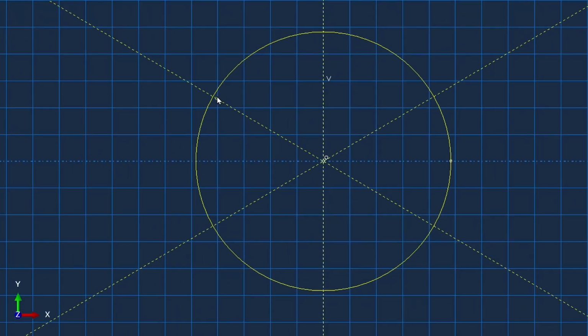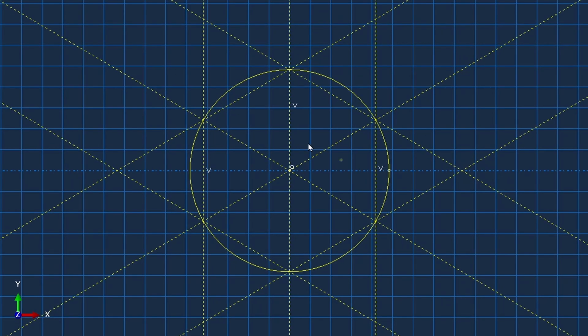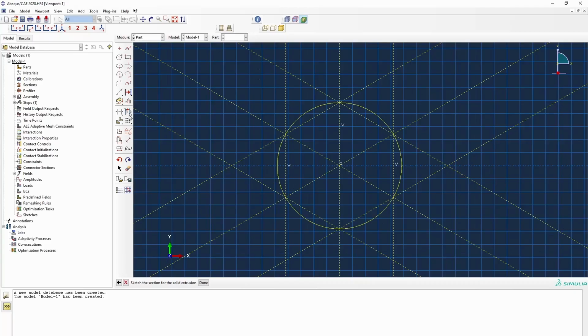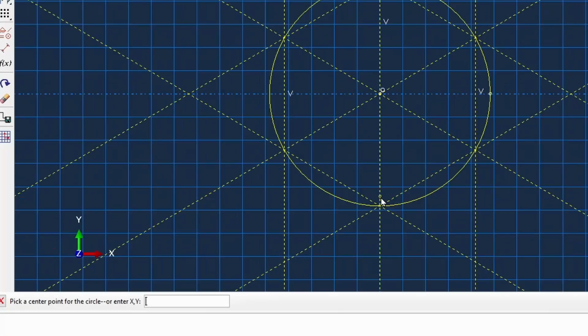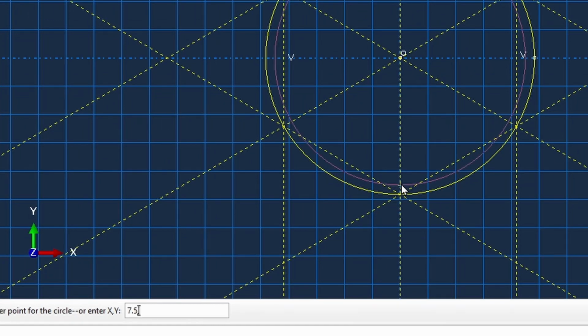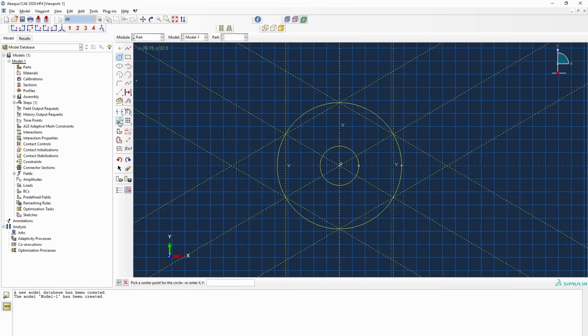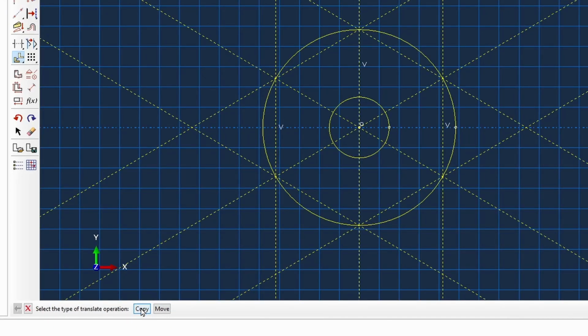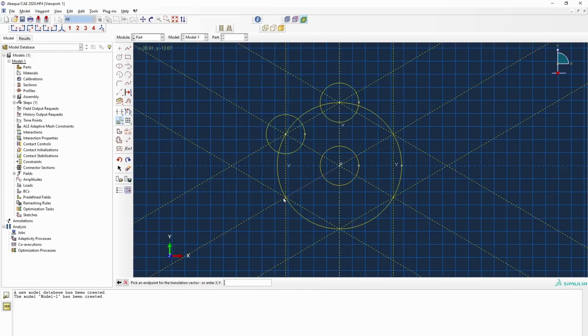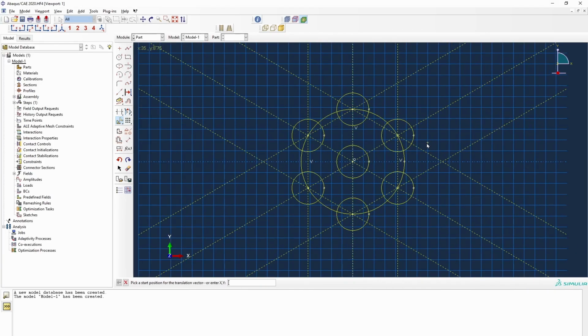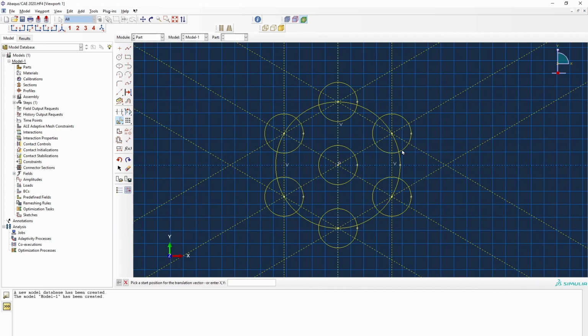So if you again go ahead and implement it this way, you can see the hexagonal arranged fibers are right there in the middle. So we can then go and say, okay, this is our circle, so it's at 0, 0 and 7.50. So that's the circle. So we're going to have to translate it from where it is, from 0, 0 to that point, and we're going to do it for all of them. So this shows us the hexagonally arranged fibers and everything in place.